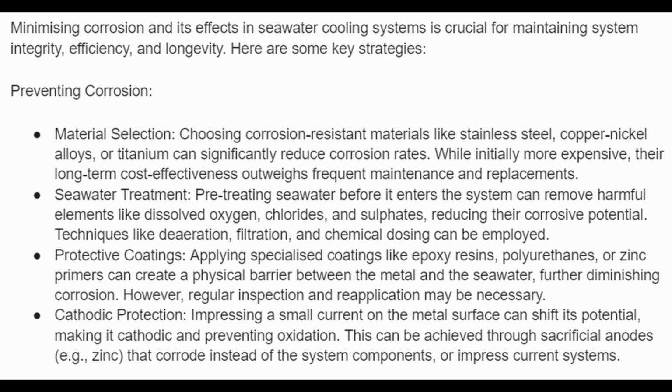While initially more expensive, their long-term cost-effectiveness outweighs frequent maintenance and replacements. Seawater treatment. Pre-treating seawater before it enters the system can remove harmful elements like dissolved oxygen, chlorides and sulfates, reducing their corrosive potential. Techniques like de-aeration, filtration and chemical dosing can be employed.